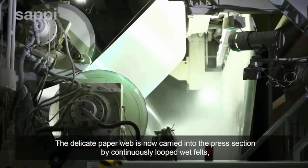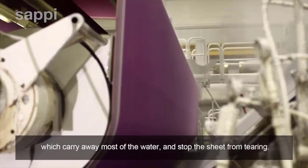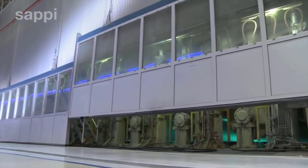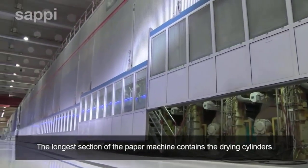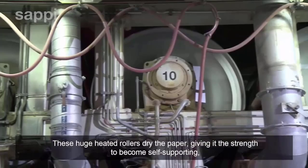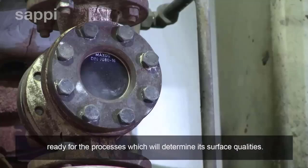The delicate paper web is now carried into the press section by continuously looped wet felts, which carry away most of the water and stop the sheet from tearing. The longer section of the paper machine contains the drying cylinders. These huge heated rollers dry the paper, giving it the strength to become self-supporting, ready for the processes which will determine its surface qualities.